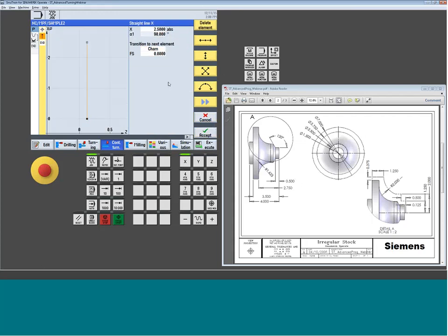So let's get our 1/8 in the positive Z. Okay. So we pulled up. Now we're up at this corner. I want to move back in. I'm going to move back in 1/2 inch. All right. Accept it. I'm going to pull out to a diameter of 4. Now, on this little part, I don't know where the end of this Z move is. So I'm going to leave it blank, but I am going to tell it the direction I'm moving in.